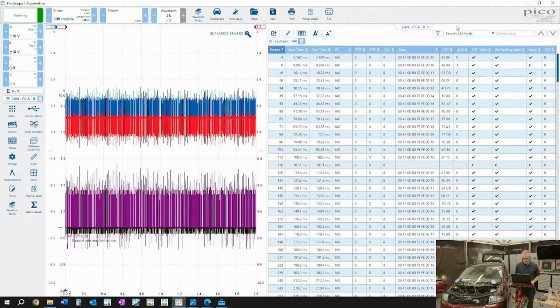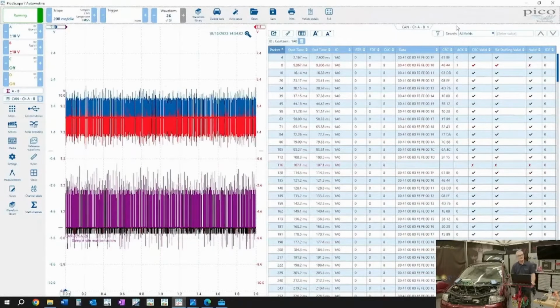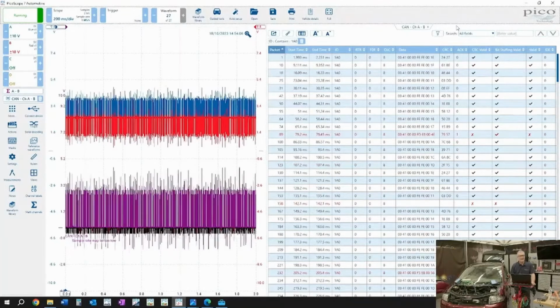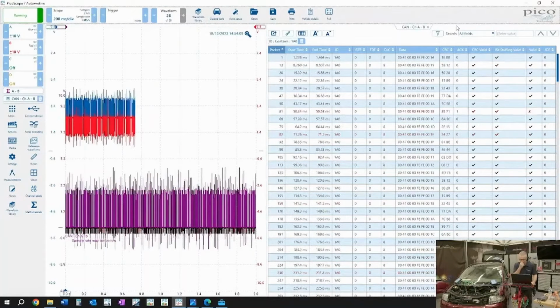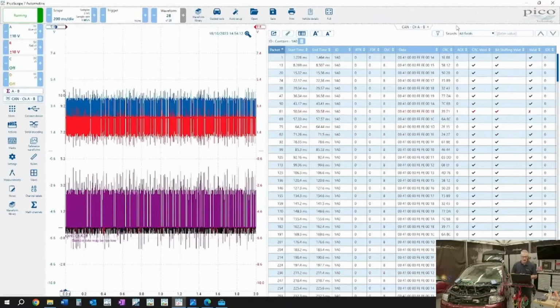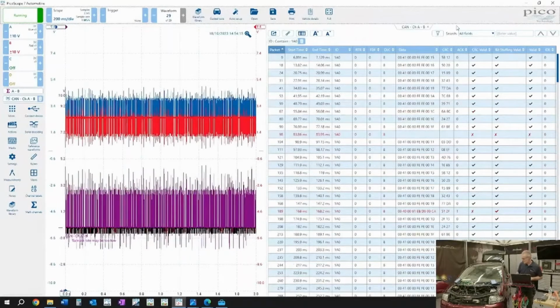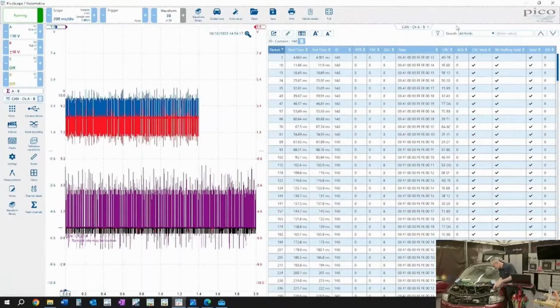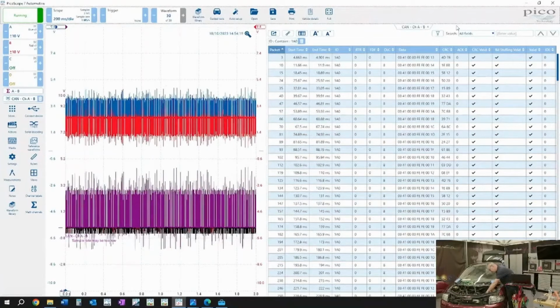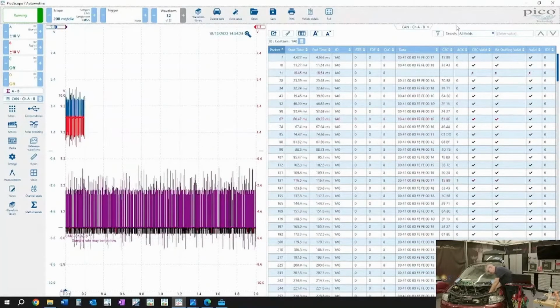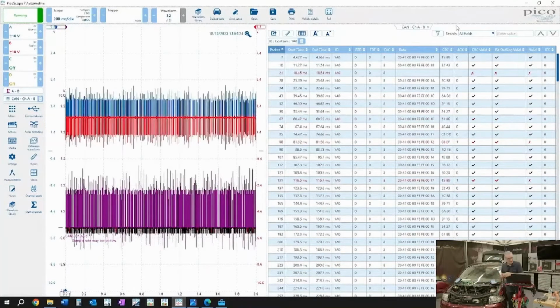What I wanted to do now was just simply disconnect the ABS ECU. He says it like it's easy, and it should be. It was working in rehearsal. Let's see what happens when we're filtering for 1A0. At the moment, 1A0 is present on the network. So I'm just going to pull the connector off the ABS ECU. Make sure we've got separation.